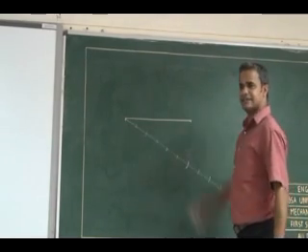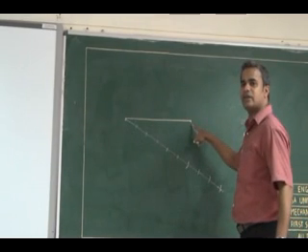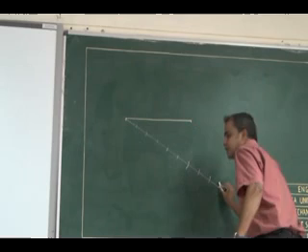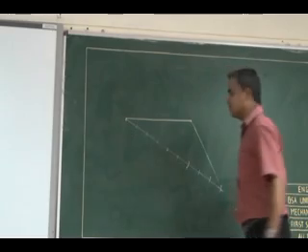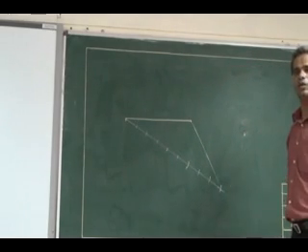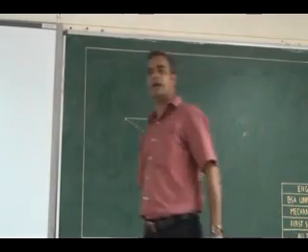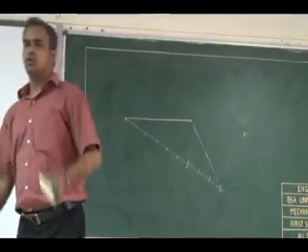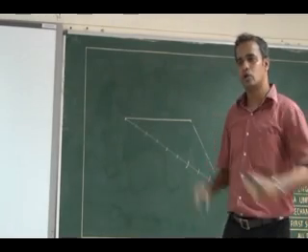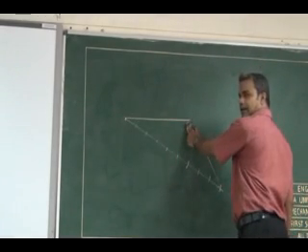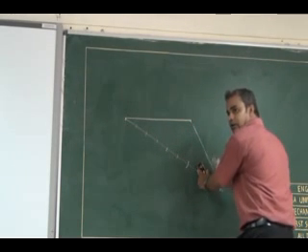Now, how do I divide the original line? The last division, I can join to the other end of the original line. I can keep my drafter on it and connect the last division to the other end of my original line. Now from here, I can fix my drafter to this line. My drafter will give me a parallel line to any line. So I fix my drafter here and move it to the next location, so it will be parallel to this line.